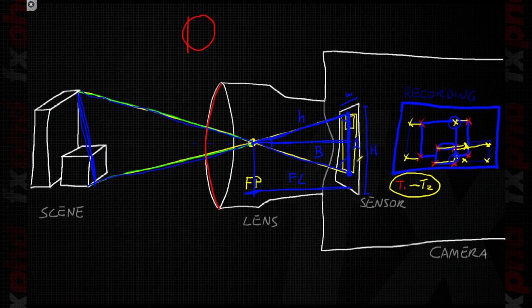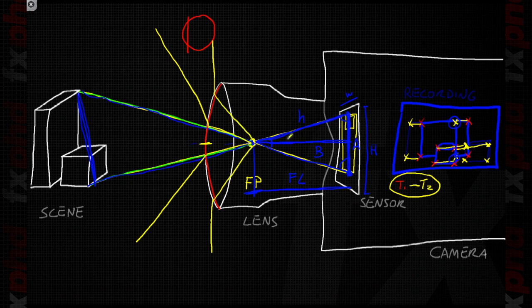The projection of this triangle in the distortion of the lenses should be something like this. Which means the farther away you are from the center, the axis of the lenses, the more distortion you are going to get. And this is actually a real problem for the calculations of the triangle, because we said that we can project this small triangle inside the lenses outside, but we know that if we project this with the problem of the lens distortion, this is not a triangle anymore.